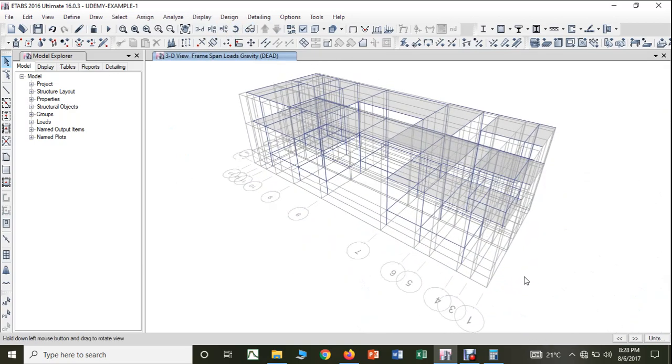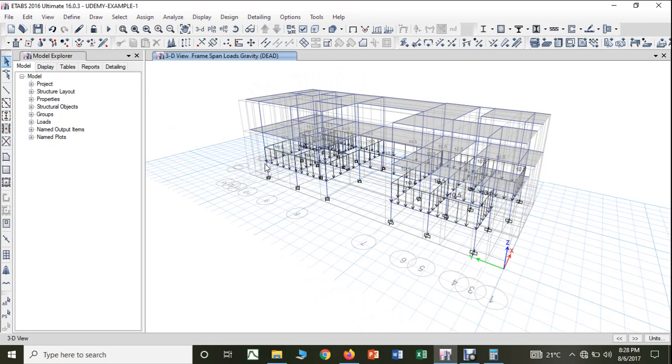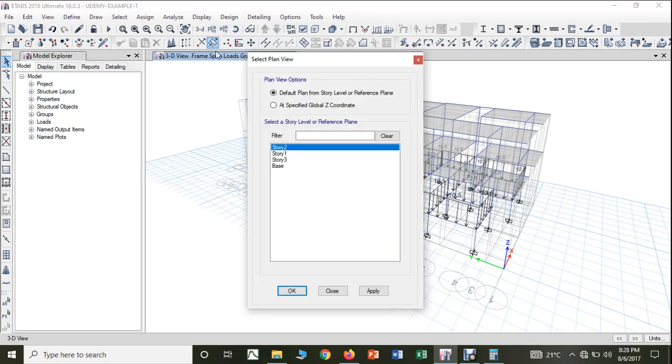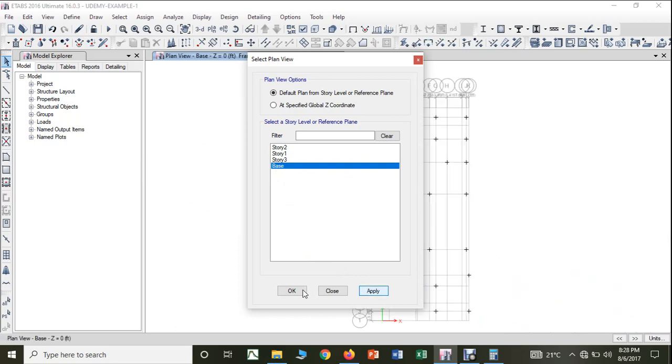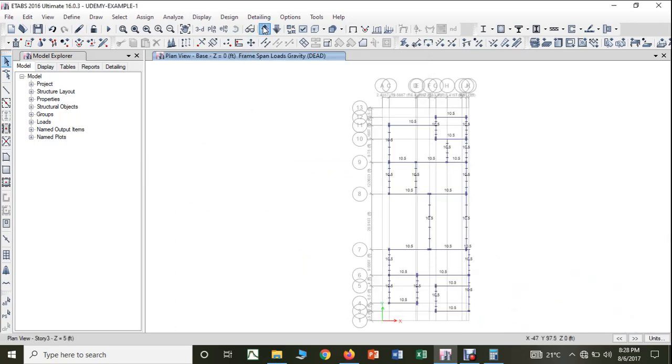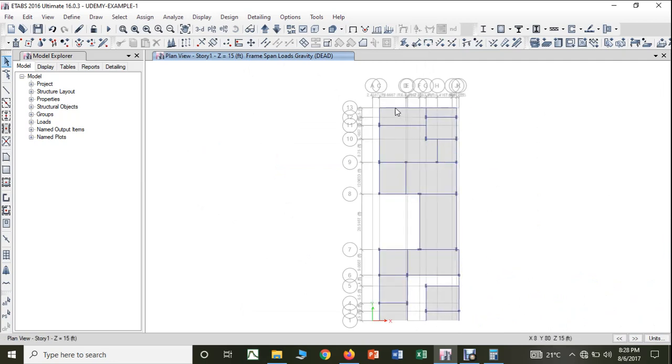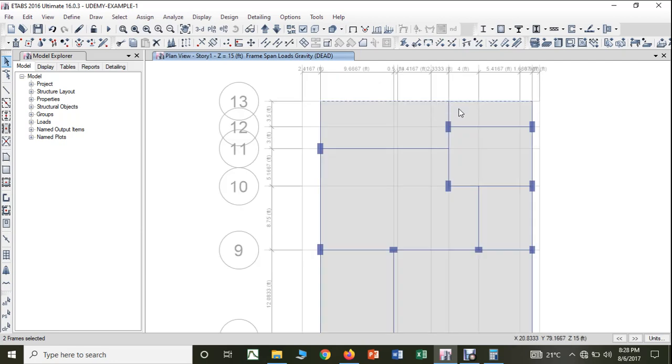Okay, so this is on the plinth beam, that is whatever wall loads are there, that is ground floor wall loads, that has been applied on the plinth beam. Now this wall load I also have to apply on this beam. So therefore now again I will go to plan, right? So this load has been applied. So now I will go to this, then again I have to choose the walls here. Here wall is there, here wall, here, here.